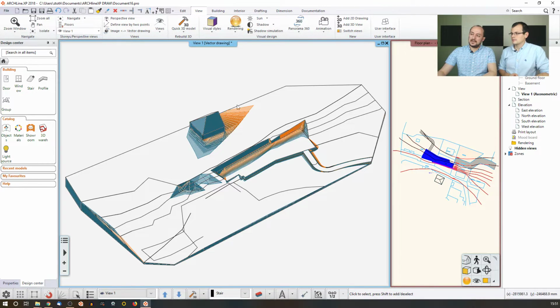Based on my settings, I get this. So I know that the sun starts from here, moves around like this, and that's the first shadow at 8, and that's the last shadow at 4:13. And if my building is here, I can see this other neighboring building has no effect on my building. And the same way I can check if my building has effect on the other buildings.